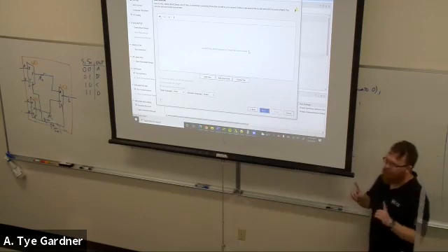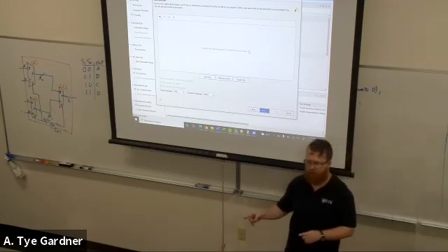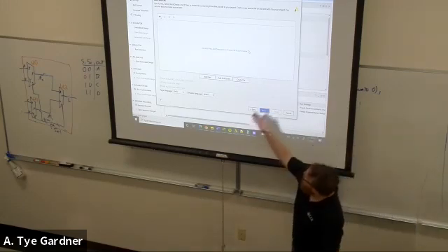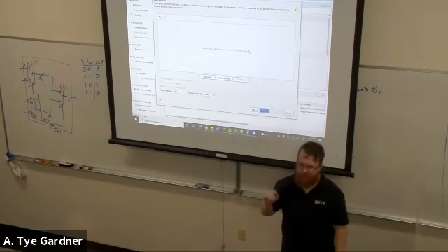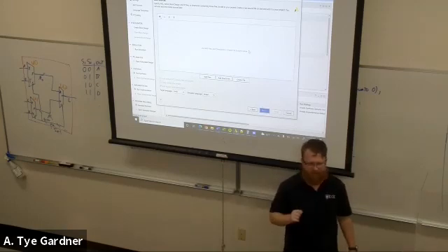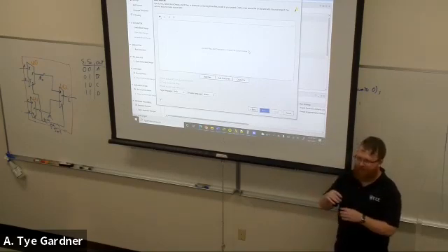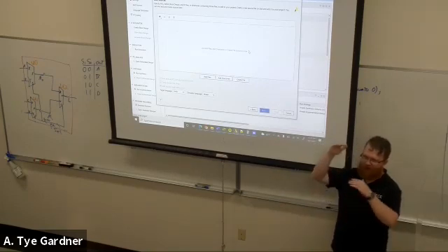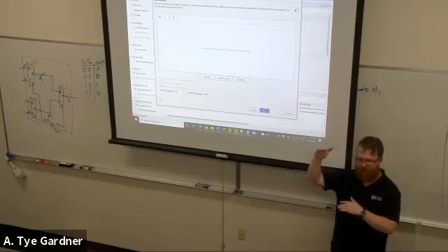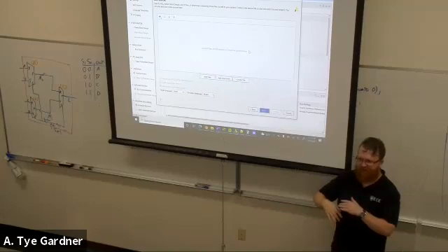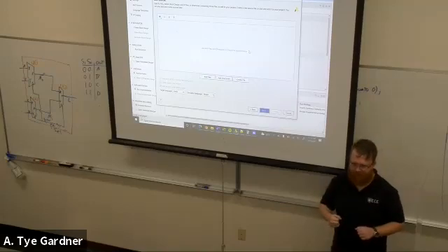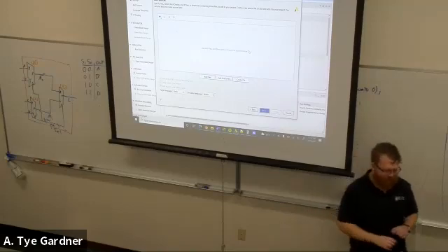Sources. Your sources are any modules that you want to use. So see how this says add sources? You can add them here. Ironically, I highly recommend you don't do that. The reason is really stupid. If I have one module, it spews out a whole bunch of helpful code ready for you to use. If you make two, the second, third, fourth onward don't have any of that useful starting point. There might be a way around it. I don't know it yet.